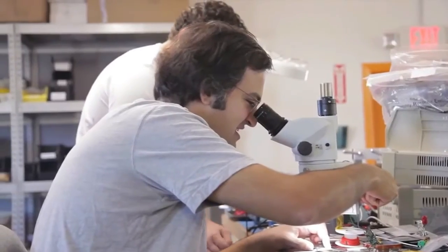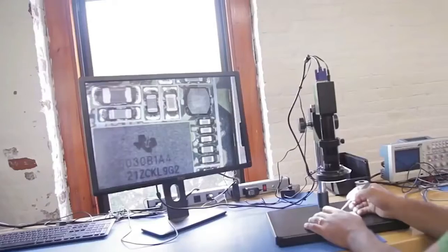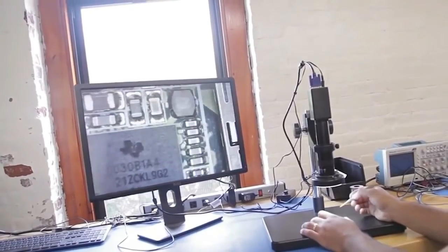When you first apply the power, it's called the smoke test. The reason it's called the smoke test is because your primary thought at that point is, is this thing going to start smoking, right? Is it going to overheat because there's some critical error or not? And so once the board passes the smoke test, you then spend time in the lab testing all the functions of it, making sure that it does what you expect. Once we have the individual pieces working, then we put them together into the complete system. So you're the technical guys behind Project Ara.